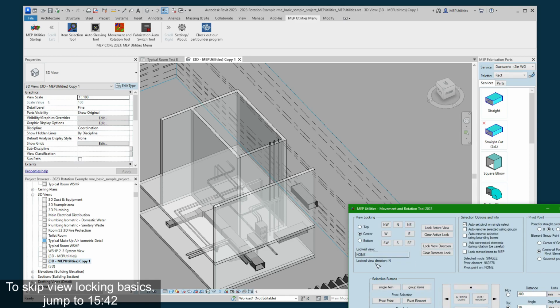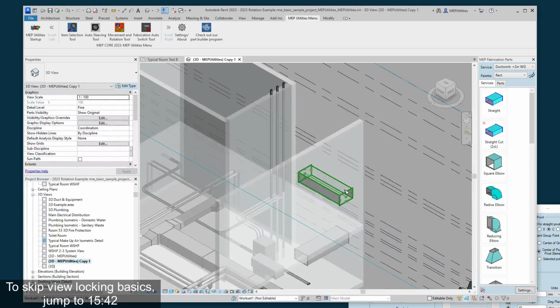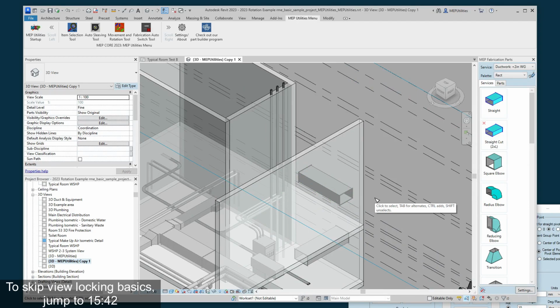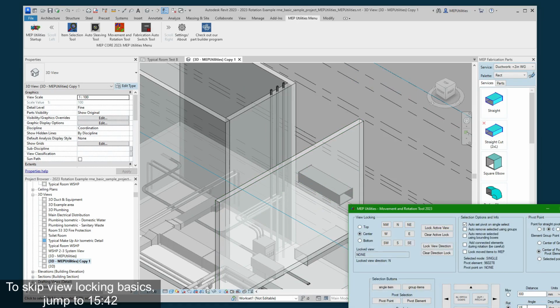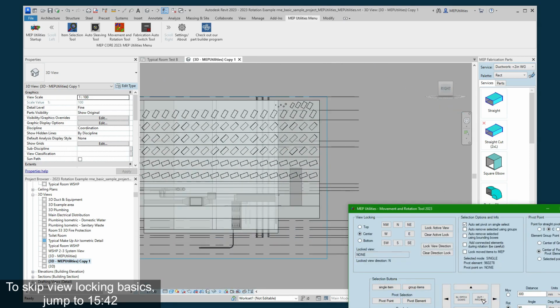So you can set your view lock to control that if you want to have a different perspective of your object in a 3D view while you're changing it by a controlled direction, such as a 90 degree. If I wanted to do a 90 degree tilt up, it's 90 degrees here no matter what I do. Even if I'm at this angle and I do the same button, it's doing the same move it would have done in that perspective.